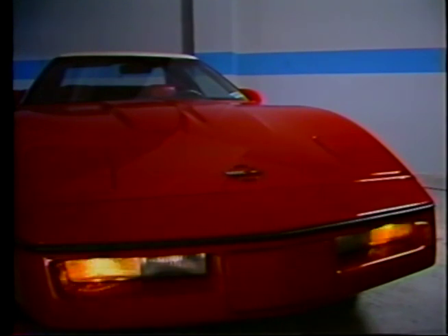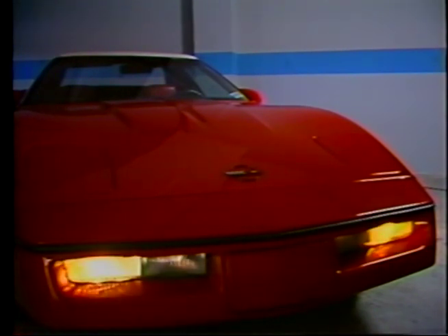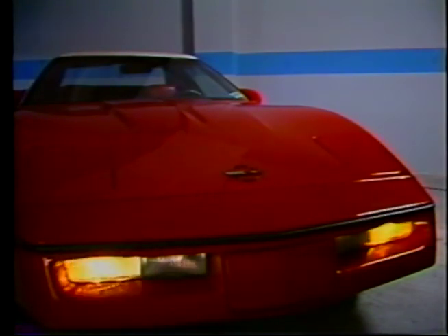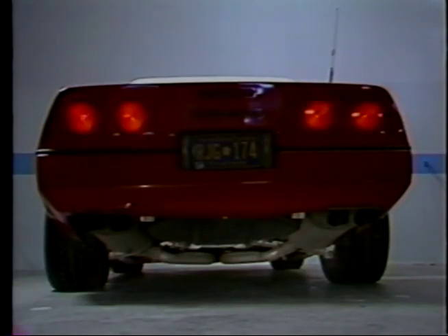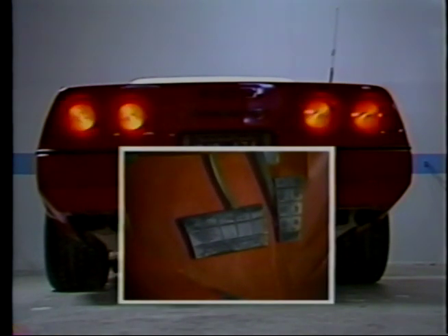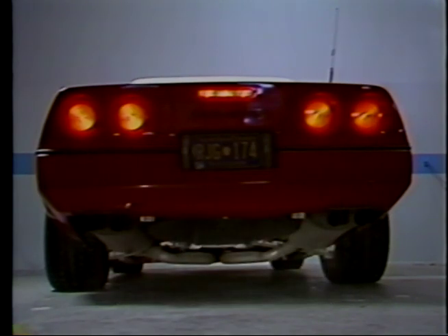What about the hazard circuit? The hazard circuit also uses a bimetallic flasher. However, this flasher operates on a higher current draw due to the fact that both sets of signal lights flash. In addition, if one or two of the lights are out, the rest will flash at the regular rate, even with the ignition off. The hazard circuit is not controlled by the ignition switch. It's connected to the brake circuit, so that application of the brake removes the four-way flasher and the lights remain lit as long as the brake is depressed. The directional and emergency flashers are not interchangeable.